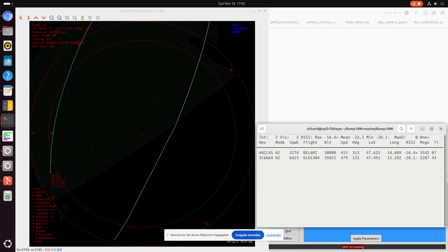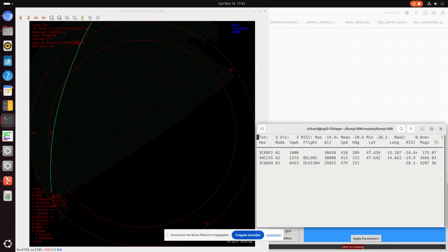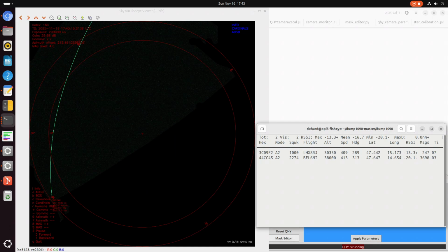Small addition on the GPS fix: you can try to shield your GPS wires and ground it. I think this can be the issue because that's a very long cable, certainly 5 meters or so, and I just wrap it in and put it in the box. I don't think that's a good idea. I have this issue with a lot of drone builds. Okay. Thanks for the hint. Good idea.